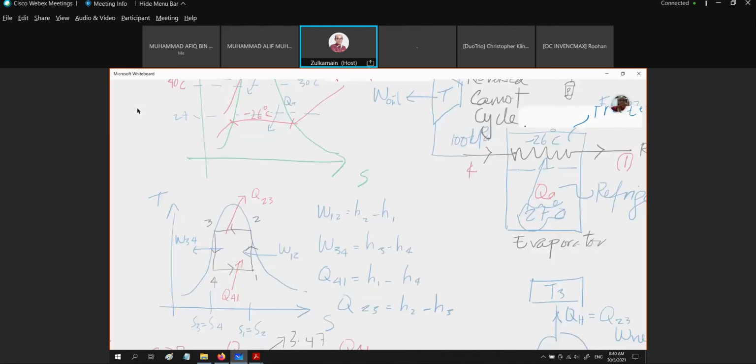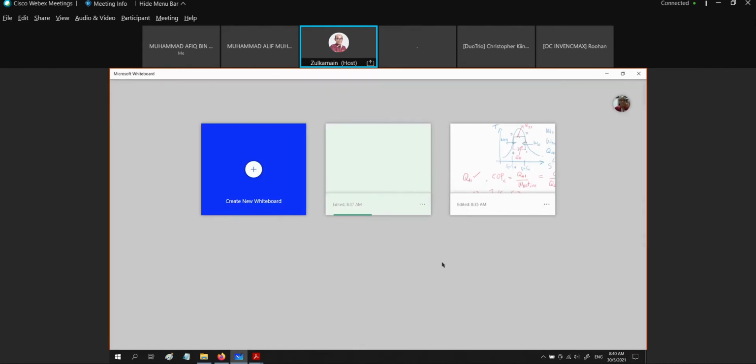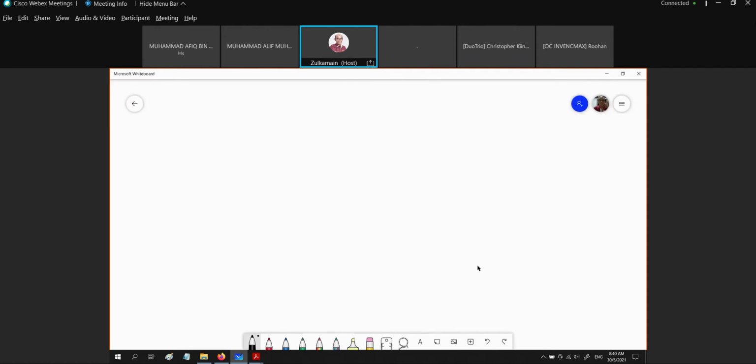If we remember what we have learned about flow devices, in the steady flow energy equation from the first law of thermodynamics, the device which can give us a low pressure is the expansion device or the throttle valve. Okay, a throttle valve. So we try to put this reverse Carnot cycle toward a more practical type of cycle. Then the schematic of that cycle will become as this.